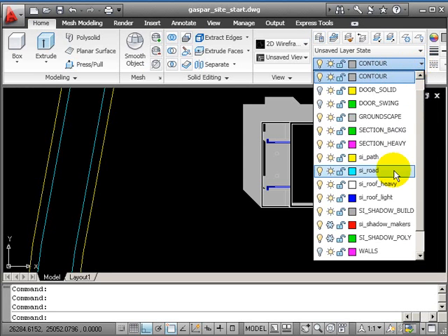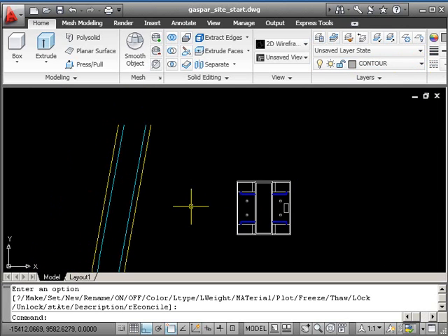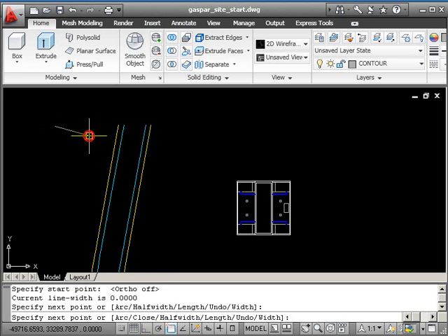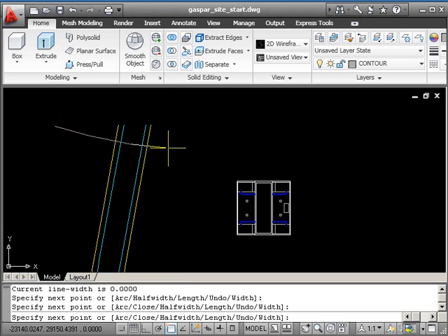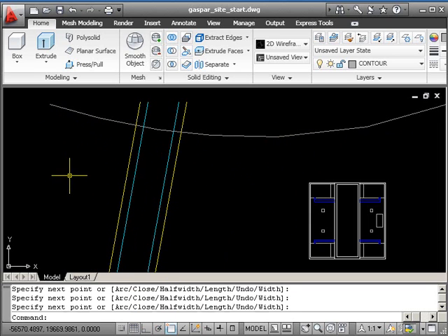Now if you turn off the shadow building just now. Okay, right, what we're going to do is use the polyline command, and these are completely made up contours. So bear this in mind. So polyline on, you could turn off ortho, and what I'm going to do is do a very basic contour. So this is ignoring anything to do with what's happening at the road. Okay, super simple.